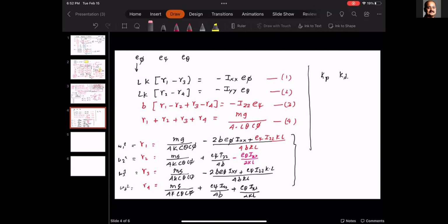From those torques, we get gamma 1, gamma 2, gamma 3, gamma 4. That gives me omega 1, omega 2, omega 3, omega 4. And I would change those values in hardware using some PWM or some type of command, and my hope is that would stabilize the quad.